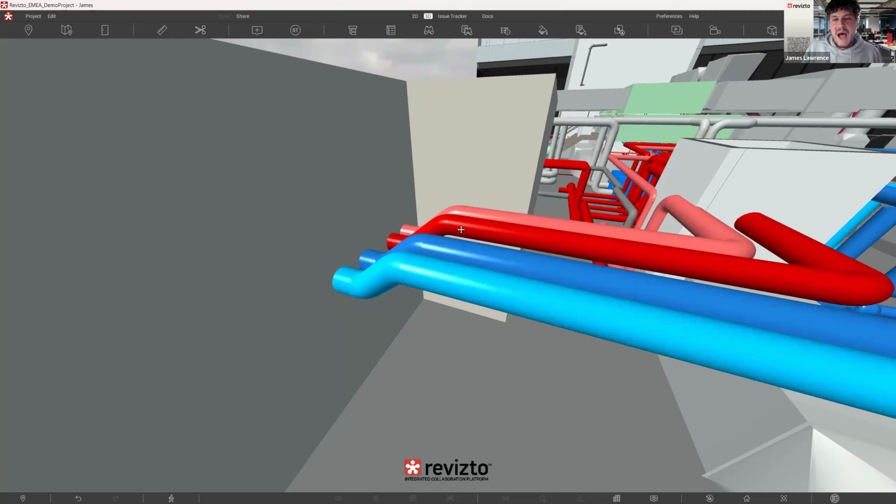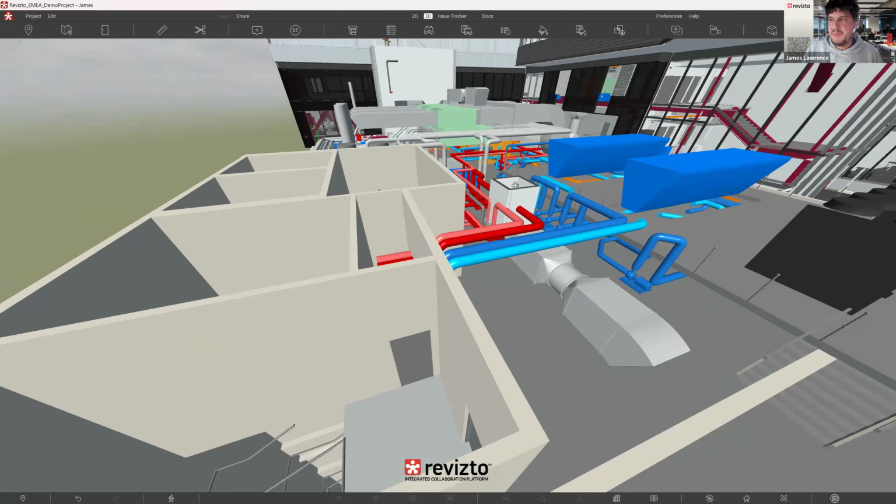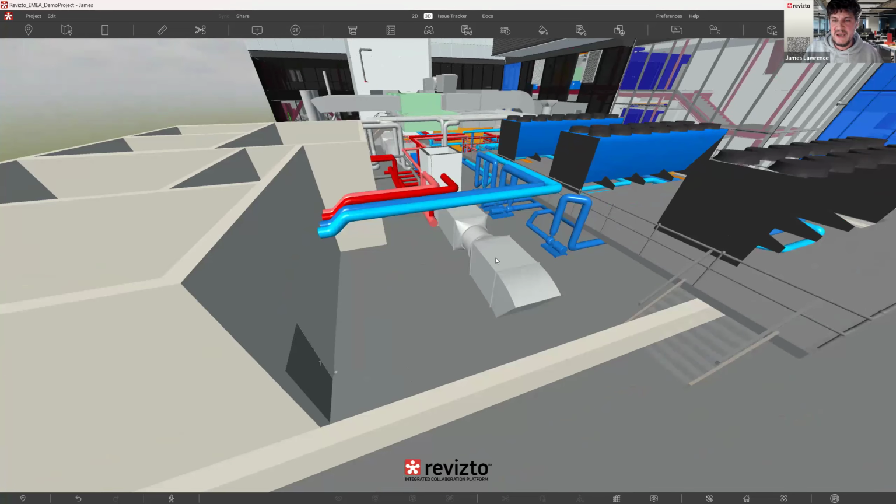One item of this development, which I feel has gone a bit under the radar, but again, I think people are really going to get a lot of use out of this, is the batch search set creator. The batch search set creator is just a fantastic way of creating batch search sets, but also handing over the responsibility to design parties, consultancies, contractors to maybe work in their own silos, especially if they're using the Clash automation and you've given them access to use Clashes. Why don't you give them the opportunity to create their own search sets as quick as possible?